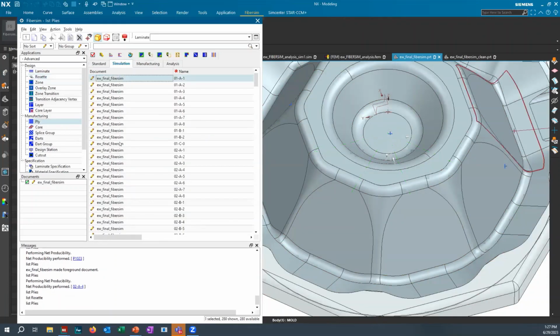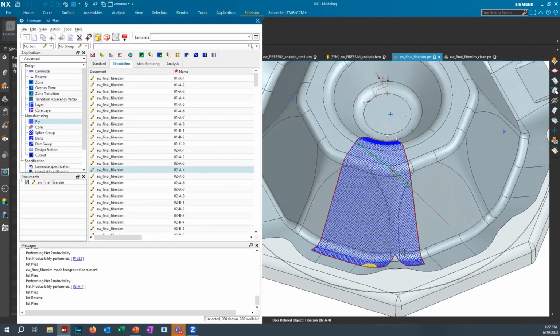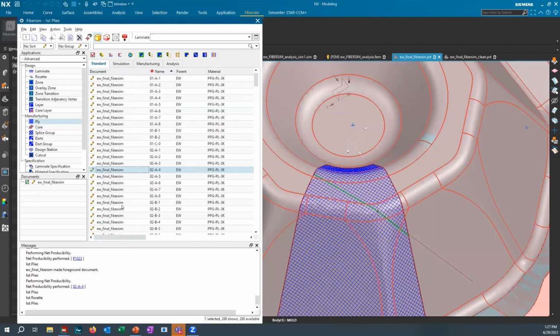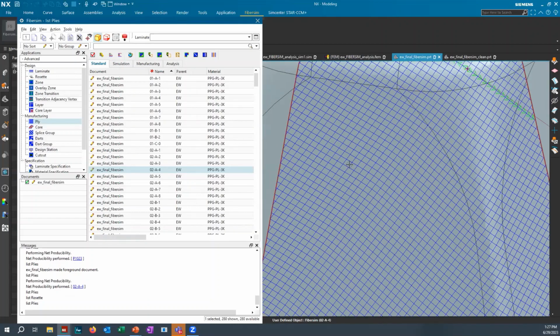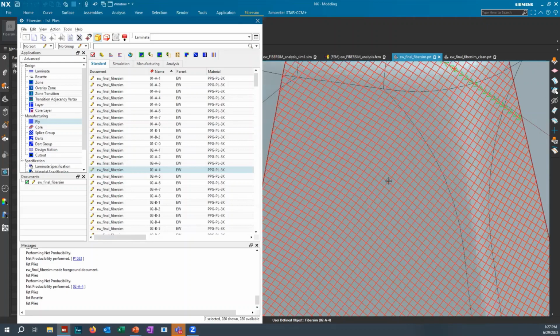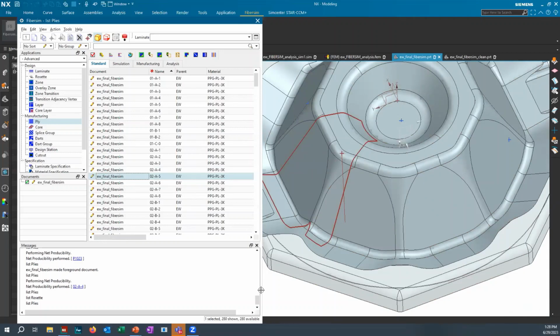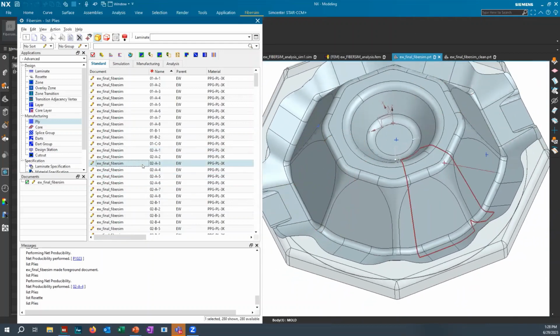But if we look at the ply itself, I can't remember which one I did. There we go. Ply 2, for instance, here, A-4, we notice that even though this is supposed to be, let's review this, a 45 ply, and if a radial rosette was coming across here, we might be deviating a little bit from this. This is probably closer to 40 or even 35 degrees. So sometimes, due to the complex curvature of this part, we had to accept that some of the plies may be a little bit off from each other in that respect.